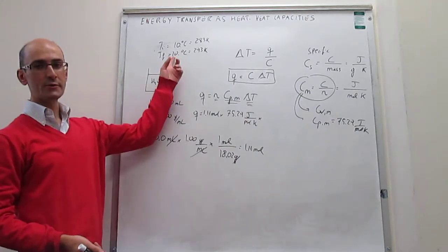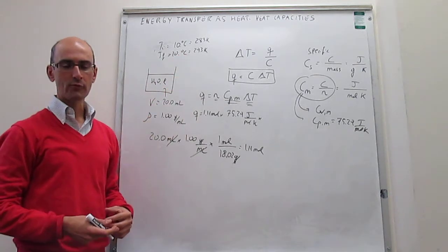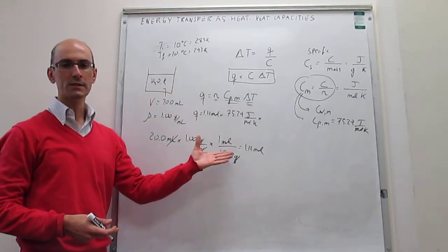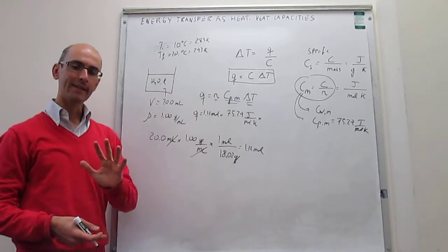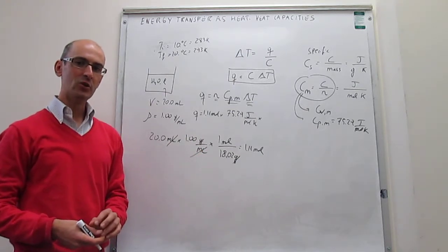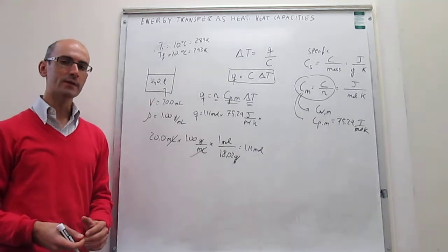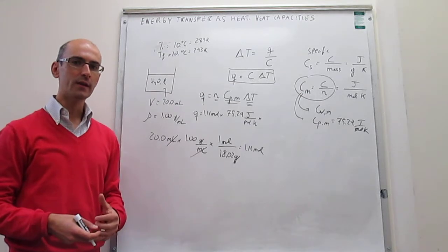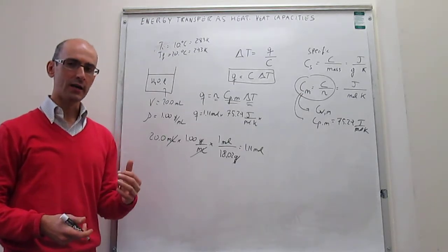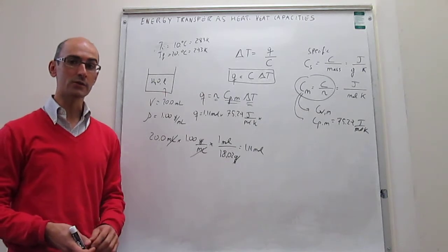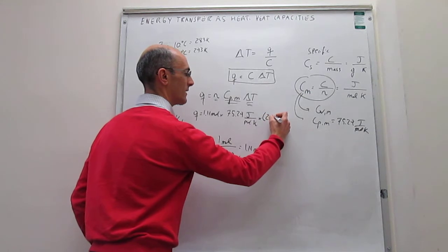Right, so the change in temperature is going to be the same in Celsius and in Kelvin. However, in some other equations that we will see, you'll have to take the ratio of the temperatures, not the difference. And in that particular case, doing the calculation in degrees Celsius will be incorrect. So just to get good training and run smoothly with these temperatures, I always recommend you to do this calculation in Kelvin.